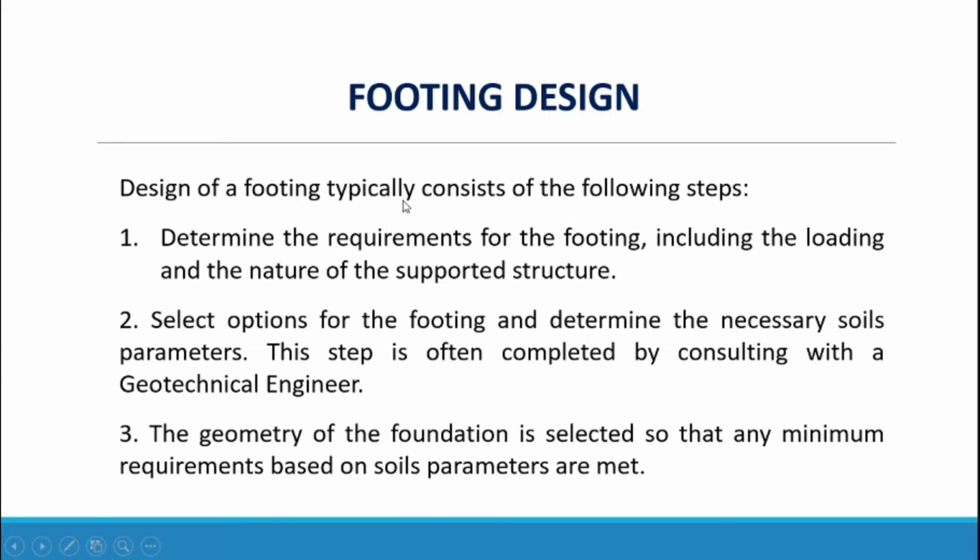Design of a footing typically consists of the following steps. First, determine the requirements for the footing, including the loading and the nature of the supported structure. Number 2, select options for the footing and determine the necessary soils parameters. This step is often completed by consulting with a geotechnical engineer. And number 3, the geometry of the foundation is selected so that any minimum requirements based on soils parameters are met.